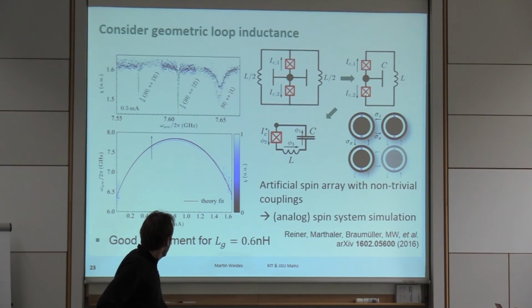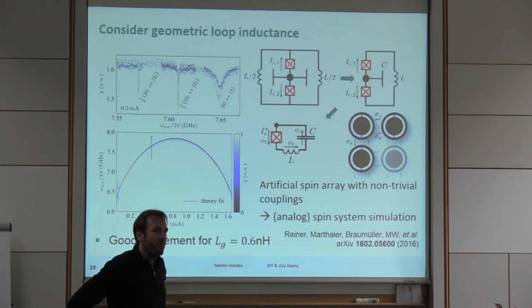I guess I would place it off-center from here, and then there's going to be crosstalk, which I have to calibrate out. But if you have 9 qubits, then I need 9 current sources, or maybe 8. For each qubit, I would need 1 current source, or 1 flux bias line.